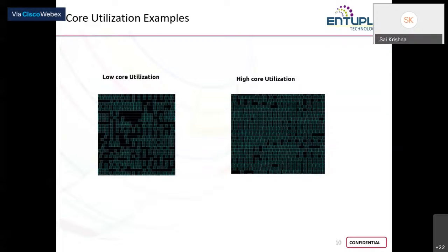Please do remember that area is of utmost importance, because even if your chip size increases by a fraction of a square micron, you will have to invest some extra amount, which could turn out to be very costly. That is why you always intend to use as minimum area as possible, as low power consumption as possible, but the best timing possible.